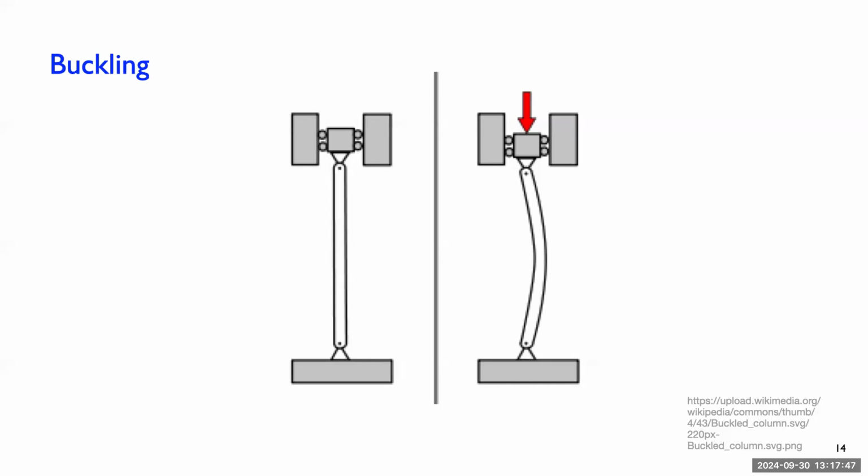But sometimes, if you know you have a solution that's going to buckle, you may artificially induce a certain direction. So you may purposely apply a small force in the out of plane direction just to encourage it to always buckle in one direction to make the results repeatable.